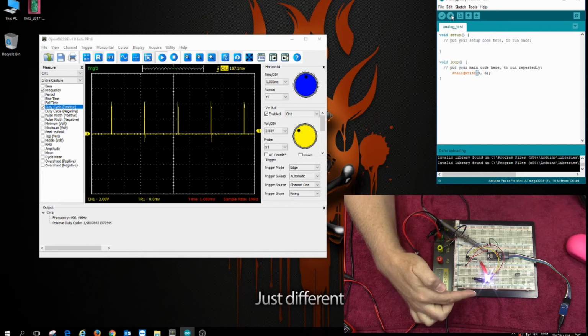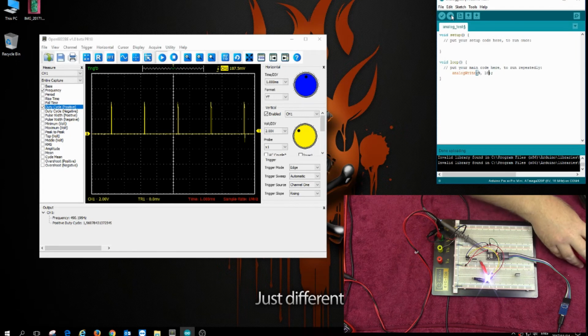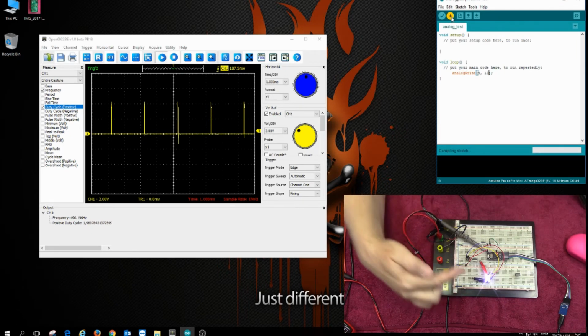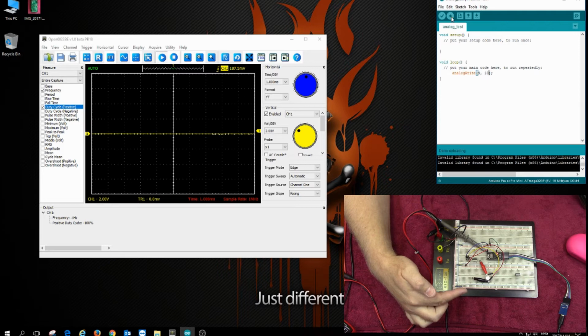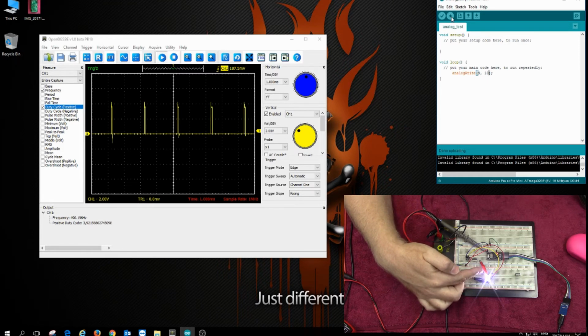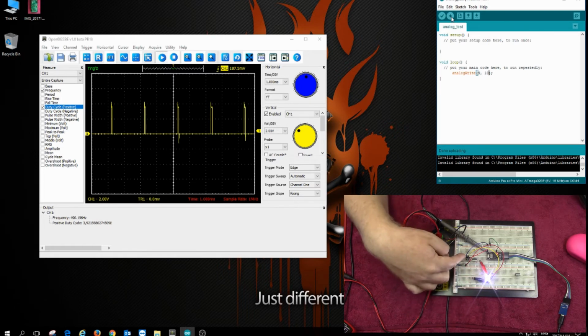So it's a little bit brighter now with a higher PWM, and I don't want to go too high because, like I say, not quite the right values. We'll take it to 10 and it'll be even brighter, but then we're starting to push the envelope of this LED without a heatsink, and you're basically getting the gist of how it can control through the MOSFET.